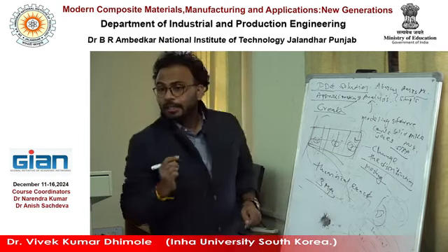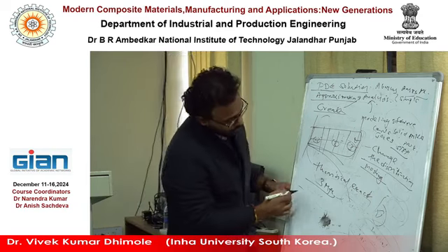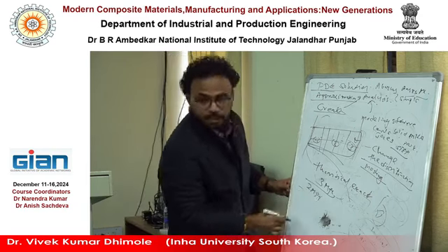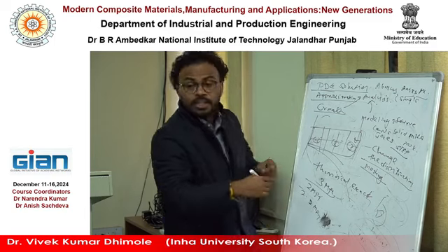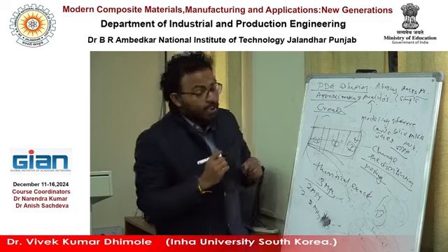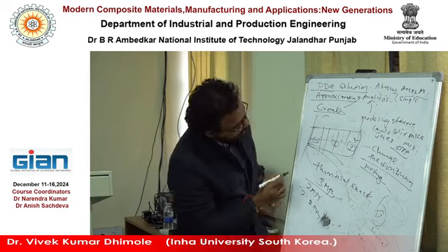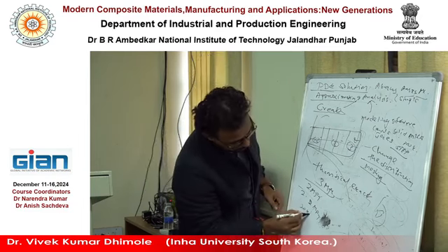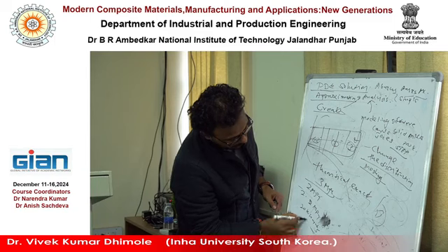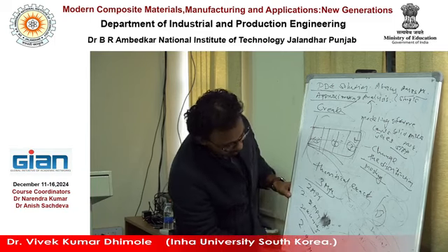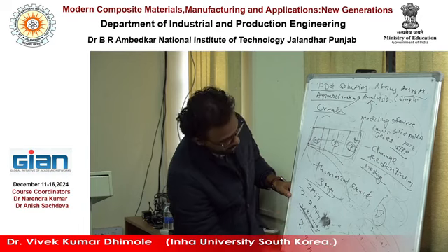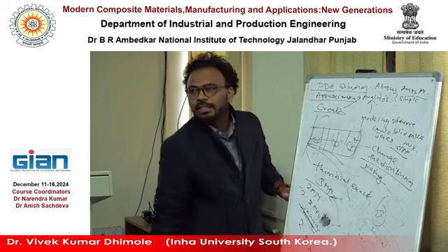When you do the finite element, suppose you have 3 elements, maybe you get 2 megapascal, right? When you have 5 elements, maybe you get 2.2 megapascal. You will increase the elements. Then you reach the point, maybe up to 20 elements, it will give you 2.98 megapascal. So that means these 20 elements reached the level of the theoretical result, right?